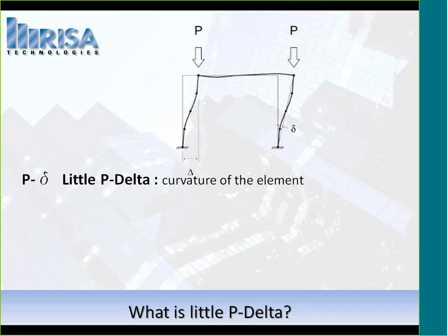So if we look at the model above, what we've got there is a big P-Delta, which is actually this little delta sign above my curvature word. That's the deflection from the top of the column, or the entire length of the member column, from that to the bottom of it. So you're looking at the entire deflection there.